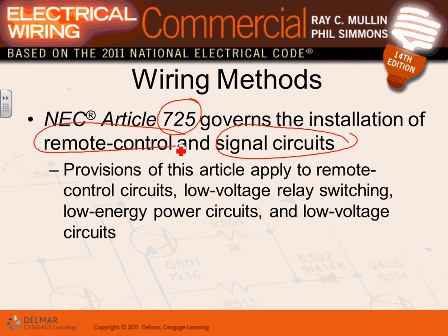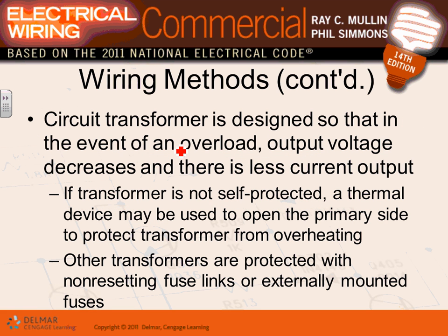We'll talk about this one, guys, as we go through too. So this covers the low voltage circuits. So the low voltage part, which is the 24 volt part, will be wired based on 725.